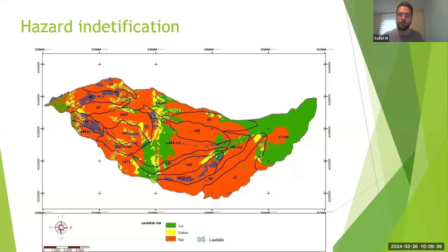Sometimes it can be as easy as googling and finding something like this landslide risk map on screen, which specifies the low risk area, the medium risk area, and the high risk area. So you design your investigation looking at the risks you're possibly going to encounter.